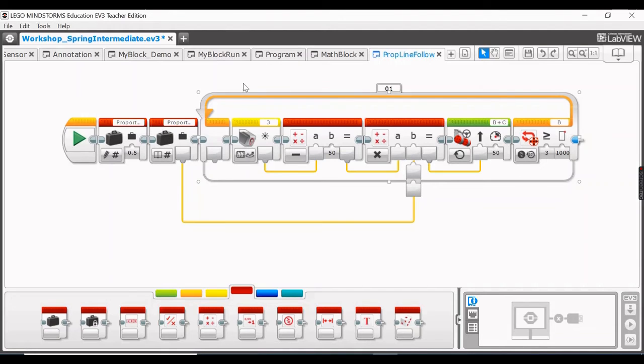Because sometimes when you have advanced lines of code where it's like sheets and sheets and it just piles on, especially in EV3 Mindstorms, it's very good to define your variables at the front, rather than going through each separate piece and changing it there. It just helps a ton. And if you want to use the variable in a different spot, all you have to do is drag it to somewhere else. So basically that's one place you can do it.